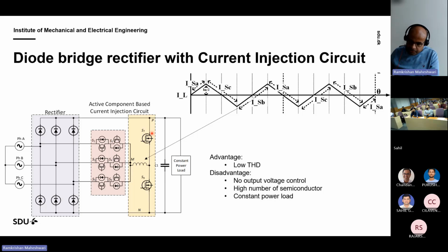So this is one thing, but what about the switching frequency here? Since they have to select the phase with the middle voltage value, they are switching at 50 Hertz. So these are low switching frequency devices. So switching losses are not there, only conduction losses are there. So we can select a proper device for the phase selector switch, which does not have high conduction loss. Silicon carbide switches, we go for high switching frequency. So a device with low conduction loss fits very well here.